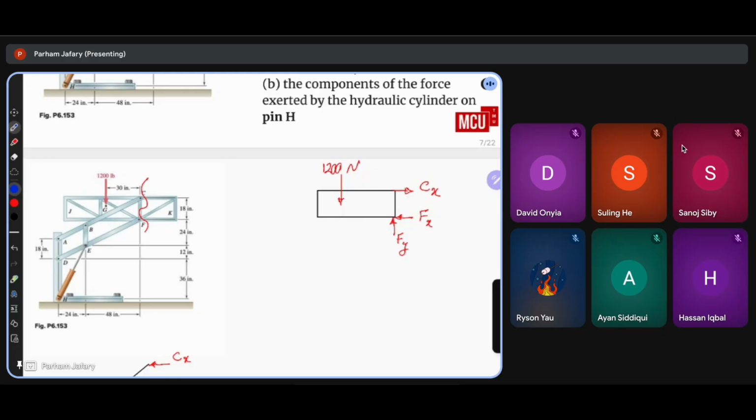Bar BC, because I'm solving basically in this frame separately. Okay, so there are two frames connected to each other. We can write the equations for each frame separately, right? So each frame needs to be in equilibrium on its own. Okay? So what I will do, yeah.